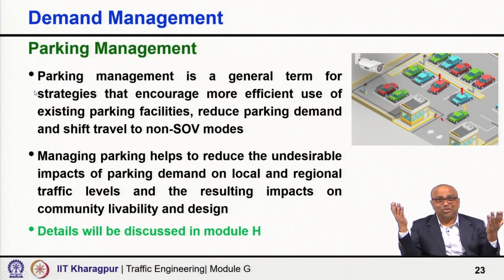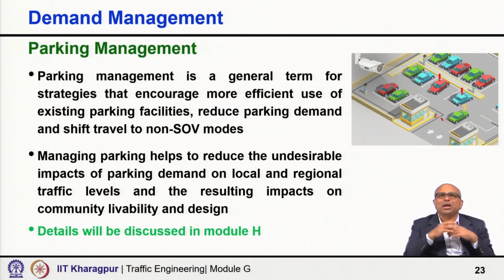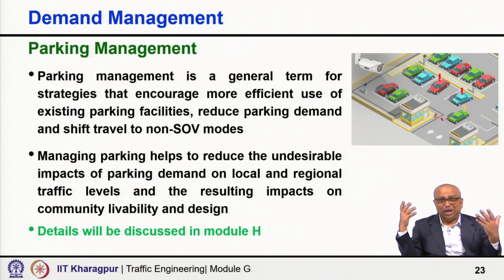Next strategy, the last one, is parking management. Parking management is a general form of strategies that encourage more efficient use of existing parking facilities, reduce parking demand, and therefore shift travel to non-SOV modes. You are taking your vehicle, but if you cannot park, what will you do? You will feel discouraged to take your vehicle, as simple as that. So, can we just do that?